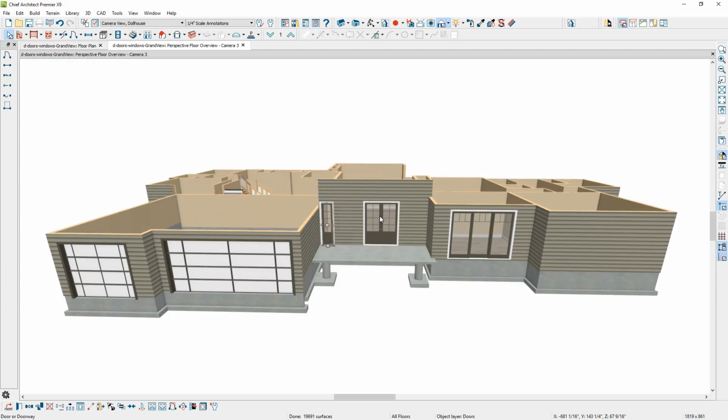Let's go ahead and select our main door. Use the center tool. Let's center that on the center of this room, and then I'll bump the side light door over. And I'm going to use the copy and reflect tool to reflect that around the entry door, using the copy tool, reflect tool around the center of the door. That's a quick way to place that other side light. Now I'm going to come back and place a couple of windows above that.